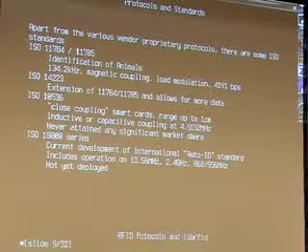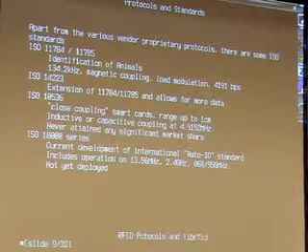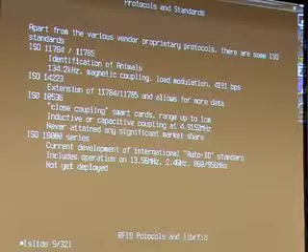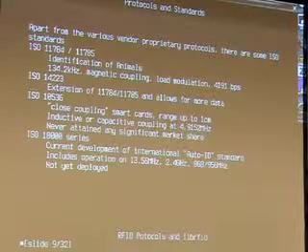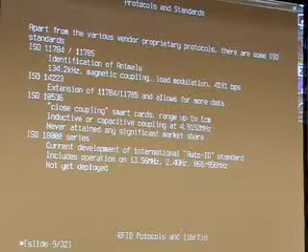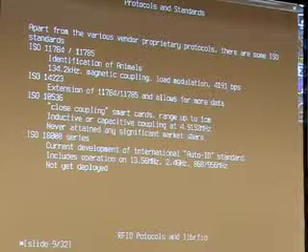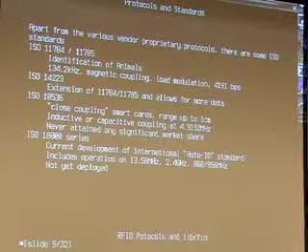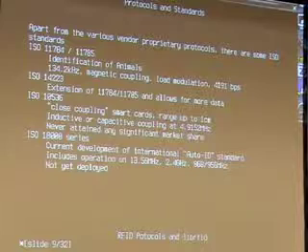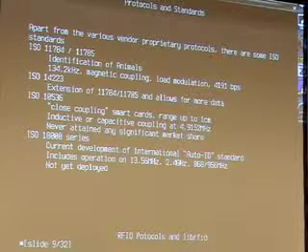It's just some unique number to identify the owner of the dog. There's an extension which allows you to put more data into that. It's called ISO14443, and then there's a standard that almost nobody knows of. It's ISO10536, which is close coupling up to 1 centimeter, which is not really very practical. I mean, if you need to be as close as 1 centimeter in order to make the device work, then you can use contact-based interfaces in most places anyway. I mean, no point on using an RF interface over the distance.